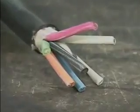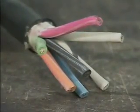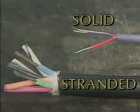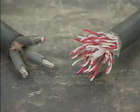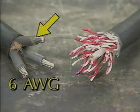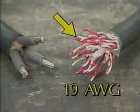Sometimes, two or more insulated conductors are bundled together in the same jacket. We'll refer to this arrangement as a cable. Cables may be either solid or stranded. Cables are described by the number and the size of the conductors they contain. The American Wire Gauge, or AWG, is a system that's used to indicate wire sizes. This, for example, is a 3-conductor 6 AWG cable. It looks very different from this 49-conductor 19 AWG cable.